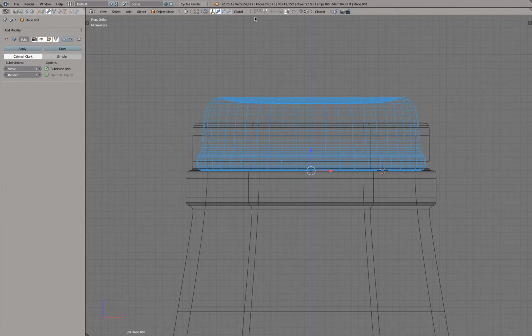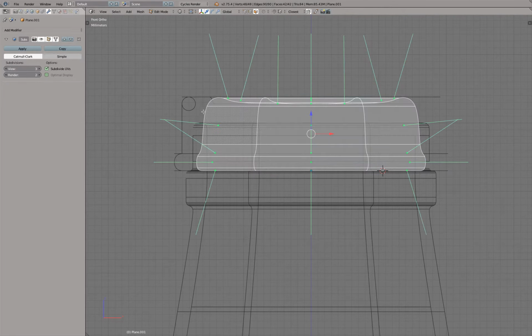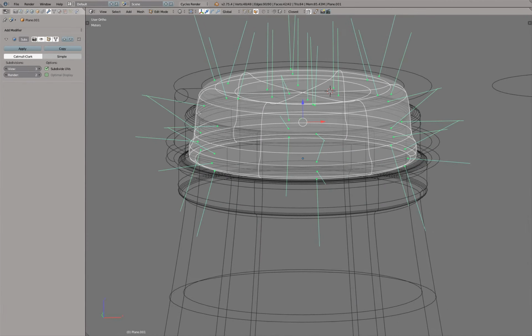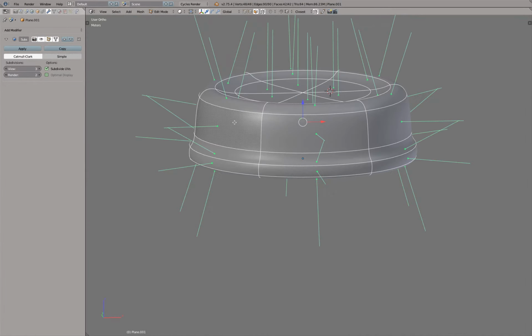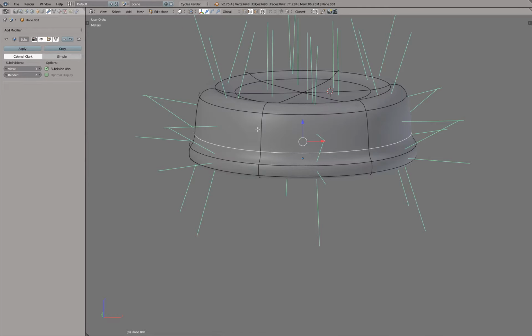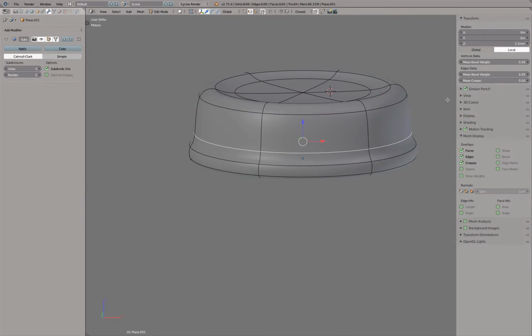Now we have to actually adjust again the dimensions a little bit. So with everything selected, let's see what we can do. We're going to do the following. I would like to have a sharp edge actually along this edge. Let's turn the normals off for a moment. And I'm not going to add actually a bevel modifier in this case. I'm actually showing you what edge creasing means.